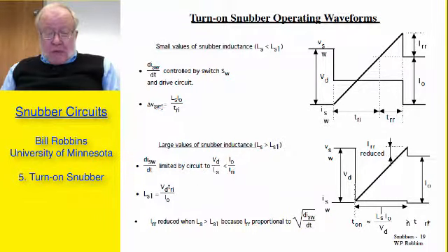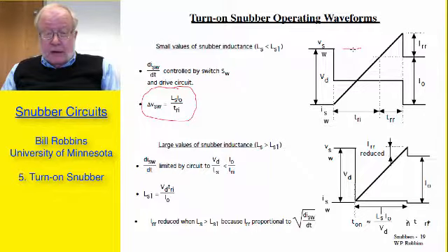The voltage drop that we engender is given by this. This is the drop that I'm talking about from here down to here. And as you expect, it's equal to L times di dt. Now, I guess I can't draw another arrow here, but that indicates the magnitude of that voltage drop.